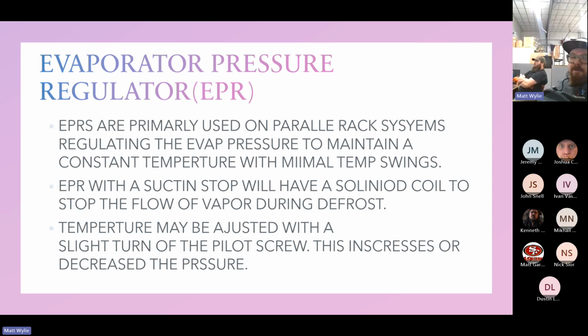EPRs are primarily used on parallel rack systems, regulating the evaporator pressure to maintain a constant temperature with minimal temp swings. I know a lot of the racks do, and also some walk-in coolers and freezers have those set on certain evap coils as well.